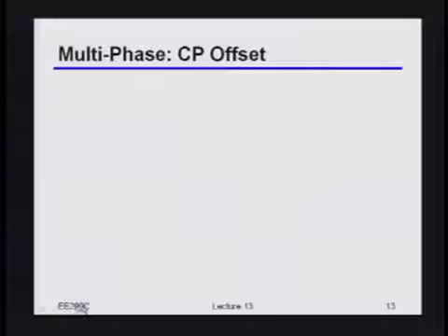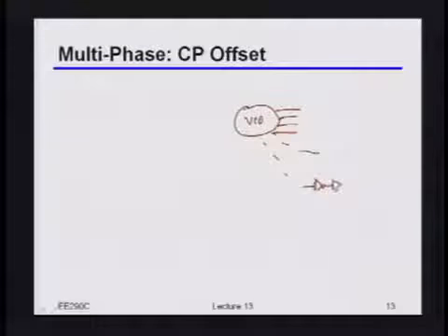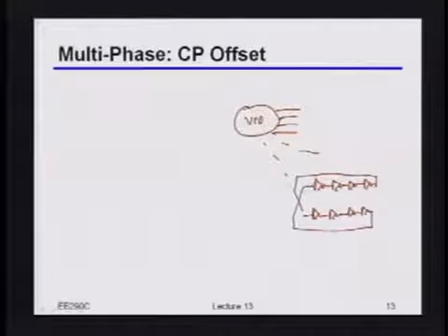What they basically do is they say, well, okay, look, if I've got some VCO that's sitting inside of a PLL, and I can somehow nominally move the phase of that VCO around, then basically automatically, if I really have a multi-stage ring oscillator, so you should keep in mind that what's inside of here is just something that conceptually looks like a bunch of inverters tied back to back. Okay, and I'll draw it so there really are 4 phases here. Right, so something that looks, say, like this.